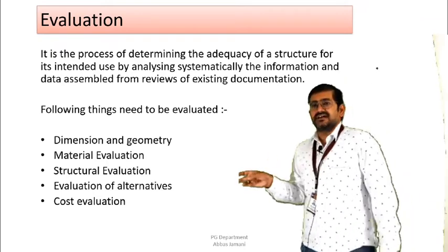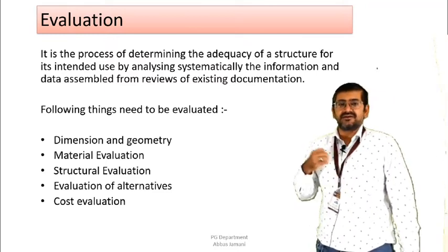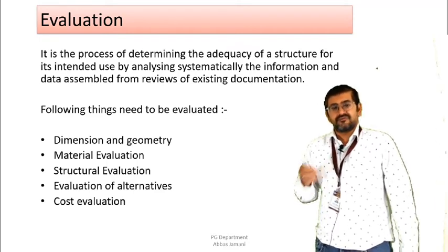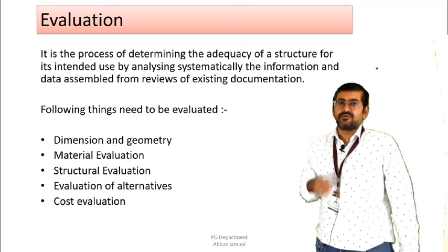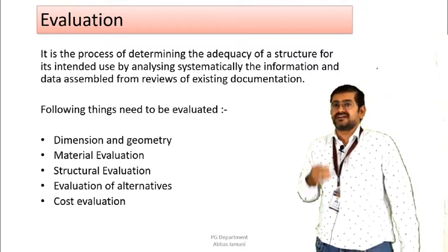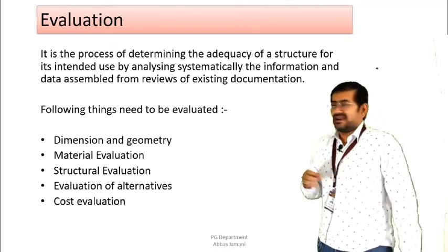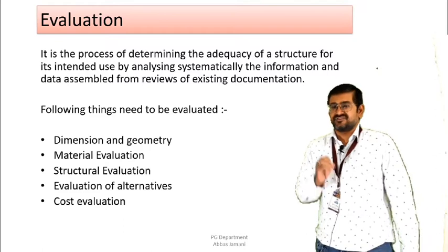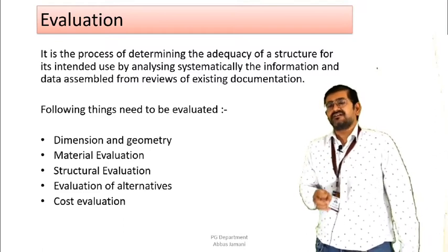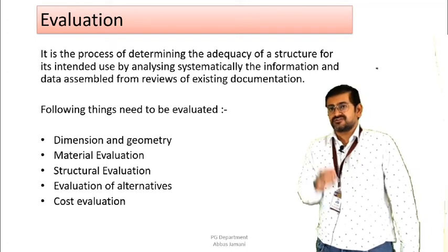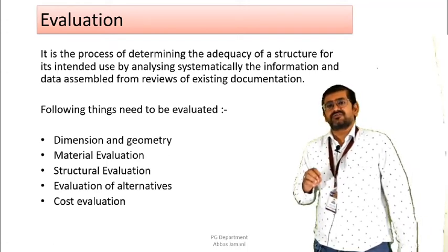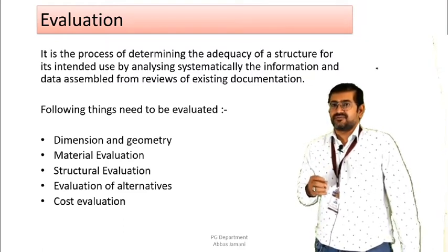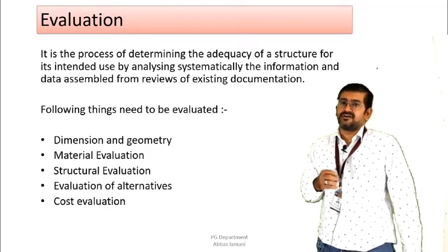Then you also check the evaluation of alternatives, that is, for the rehabilitation process that you are proposing, whether there is an alternative which is going to be more economical, faster, and more feasible. Then you look for that alternative also, because you cannot always go with one answer. You also need to have a backup option, right? And last is the cost evaluation. That is, for example, you are proposing a certain type of rehabilitation or re-strengthening process. Then what is the cost associated? What is the time that is going to be required? What are the pros and cons of that particular thing? Is the operation cost also going to be affected or not? All these different things have to be evaluated along with the engineering services that you are going to provide. This needs to be considered in the category of cost evaluation.